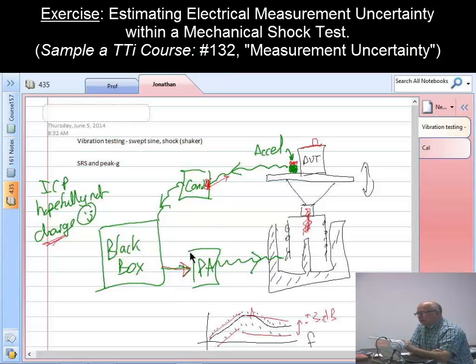Into the power amplifier, and now this is going to have some interaction backwards and forwards with this big hunk of metal that's flying around inside here. We try to keep the weight of this thing as small as possible, but it's still big and heavy, I think is the best description I can come up with. So there is some mechanical and electrical matching between the power amplifier and the shaker, and we find that we get structure-shaker interactions and all sorts of things like that going on, part of the reason for having a controller to get away with those.